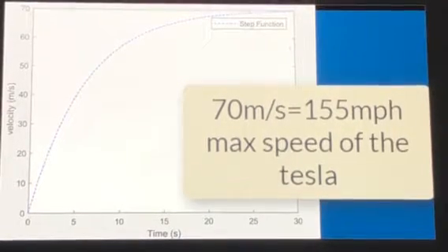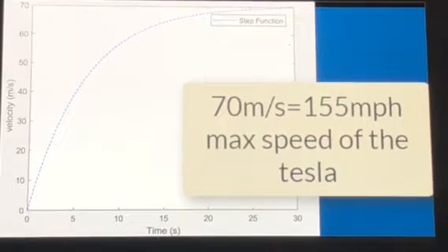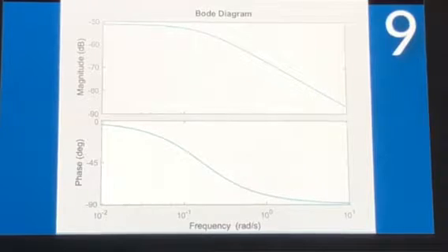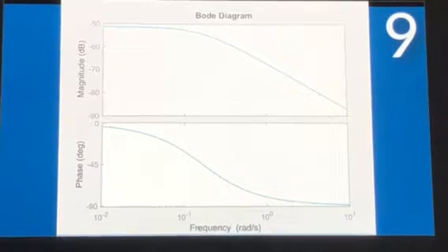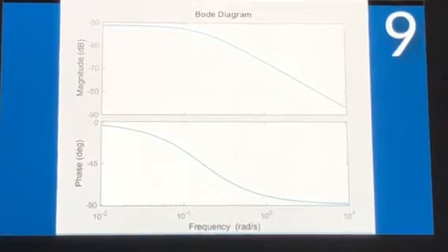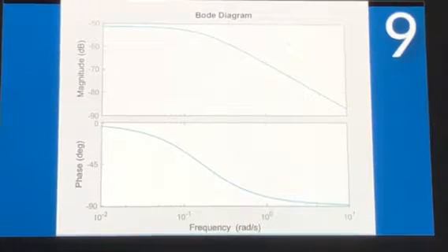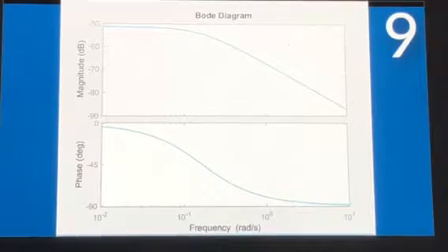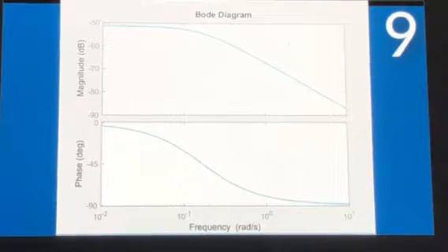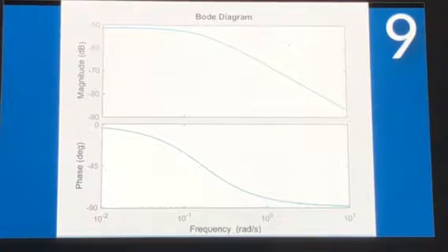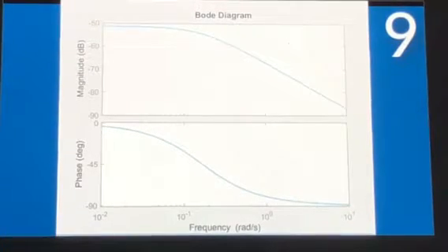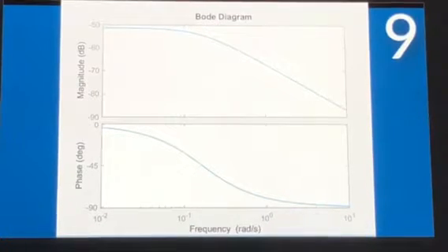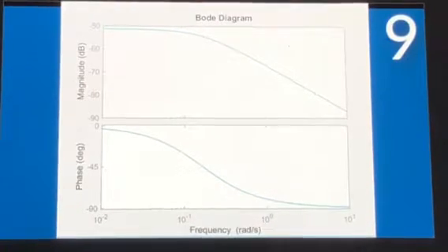That's with no overshoot. And then looking at the Bode plot of what we're doing, this works out actually quite nicely as the system is stable. As you can see on slide 9, at this point, the Bode plot is flat up on the left for its magnitude, which means it does not go to infinity. It is stable, and that's exactly what we want to see from this system. However, we still need to work on creating a system that we have actual parameters we can meet for the system as a whole.